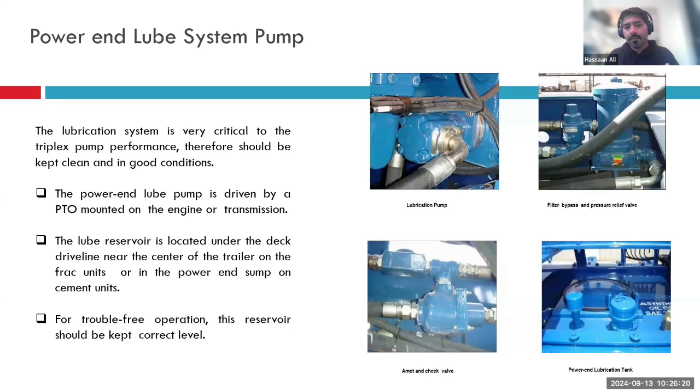One of the things which you will appreciate right over here is that there are a lot of moving components, right? They're moving at higher RPMs. There's a lot of pressure. There is a lot of conversion of the rotational motion into a linear motion. So these pumps do require a lot of maintenance. There's a very robust PM plan, or preventive maintenance plan, to ensure that these pumps are running at their optimum, and the reliability of the equipment is very much stressed upon, because you just cannot afford a failure. That's why on a lot of leases on which we have a stimulation or a cementing operation going on, you will have a spare or a backup pump.